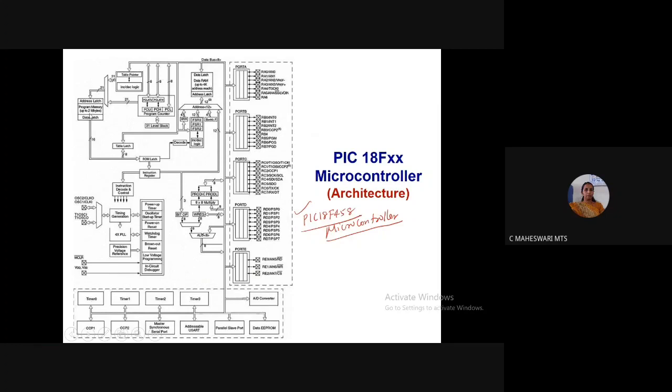This program memory is up to 2 MB. It has a 21-bit address bus and 16-bit data bus. This 16-bit data bus can be decoded and executed. This is the program counter. The program counter is used to point out the next instruction to be executed in memory. The program counter is 21 bits, divided into program counter upper, high and low, individual 8 bits. A 31-level stack is available. Table pointer and increment logic are internally available.